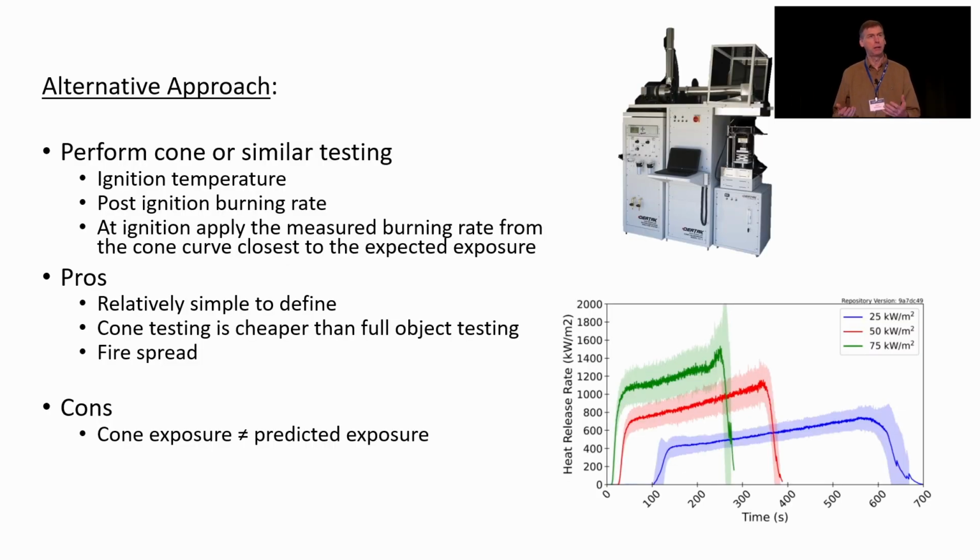And so the approach has been, and this started back when we first started out, we had this idea that if you know the heat release rate of the object that you can get from something like a cone calorimeter, in other words, you take some small sample of the seat that you're sitting on, and you put it in this small apparatus, you expose it to a certain heat flux, and then you get the heat release rate per unit area directly from this bench scale apparatus.